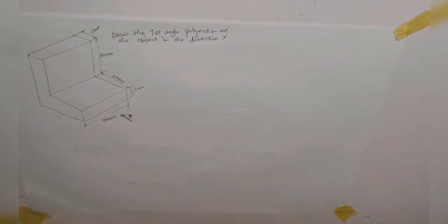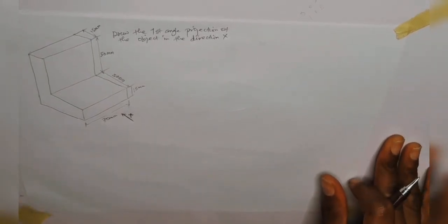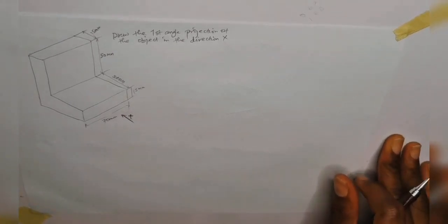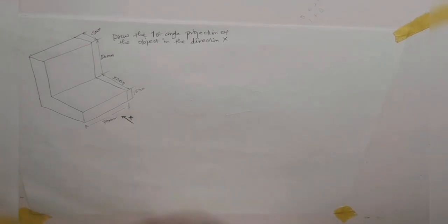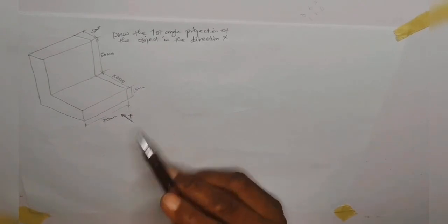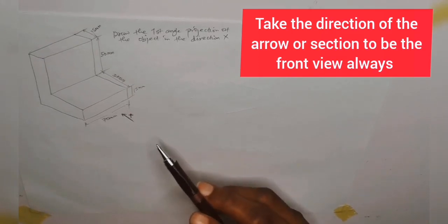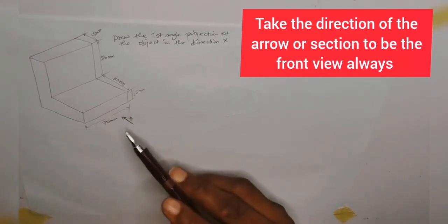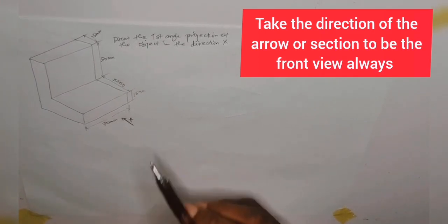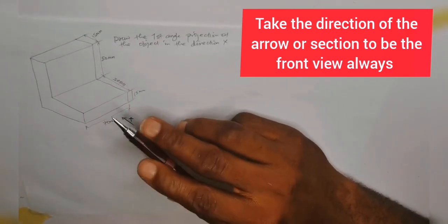Okay, now for example, if you're given a question that looks like this, they say draw the first angle projection of the object in the direction X. If they put an arrow and label it with any alphabet, maybe X, A, B, or something, it means that the direction of that arrow will represent the front view, meaning that you should take where the arrow is pointing to be the front view.